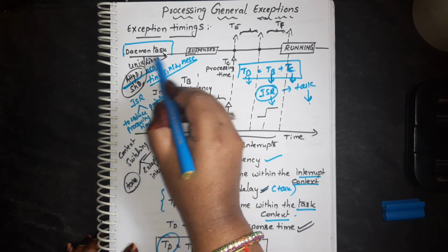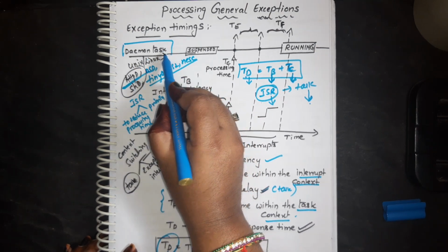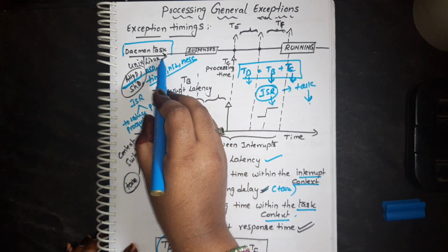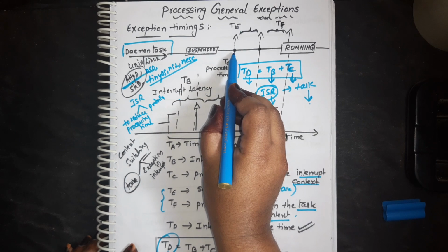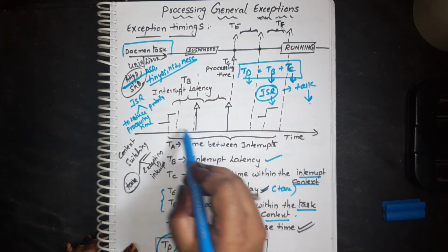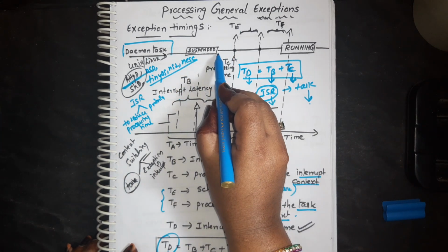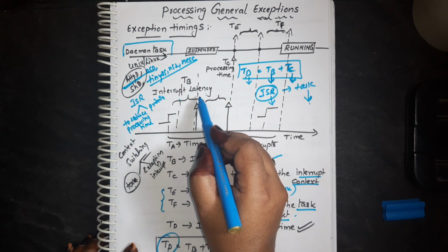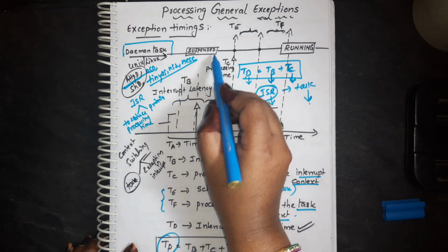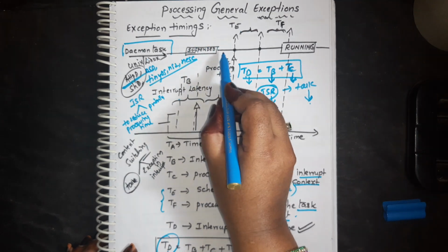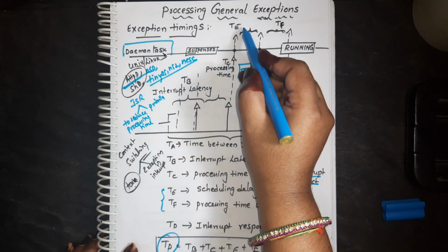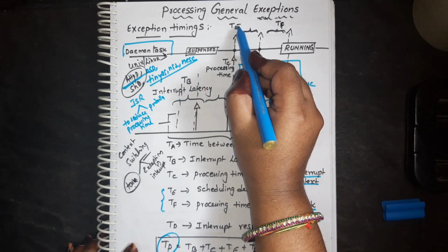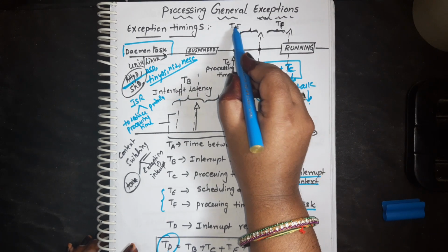So likewise we use the Daemon Task, and these tasks are background tasks which can execute with high priority. Whenever this high priority task is executing, the currently executing interrupt is suspended. So the task can suspend the interrupt currently executing in the interrupt service routine. So here it is suspended. Then the task starts, with the scheduling delay, the time of which we are going to call TE.